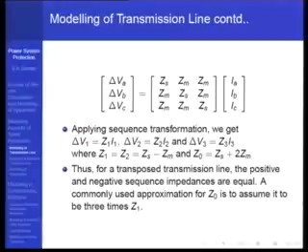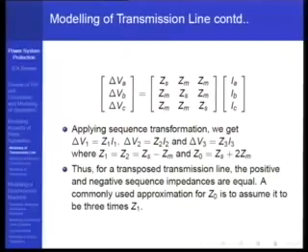With a rotating device you won't get positive sequence equal to negative sequence even if there is symmetry, because the rotor cannot run simultaneously in clockwise and anti-clockwise direction. So the moment rotor direction changes, something changes in the system even if the static part is symmetric. So positive and negative sequence impedances are identical for transmission lines and power transformers. They are the same, but the zero sequence is different.